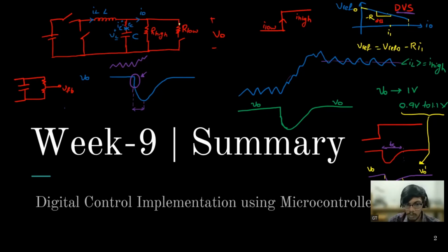voltage drop. Now say this is connected, so high current is flowing, and now I have disconnected it. So the current has a step down. The inductor current is at high current, and the output says I don't want high current, I'll only operate at low current. So where will it go? It will go into the capacitor. So the capacitor will take that current immediately, because the inductor cannot have a step function, it should be smooth and it also has dynamics. So the capacitor will take it. So now what will happen?